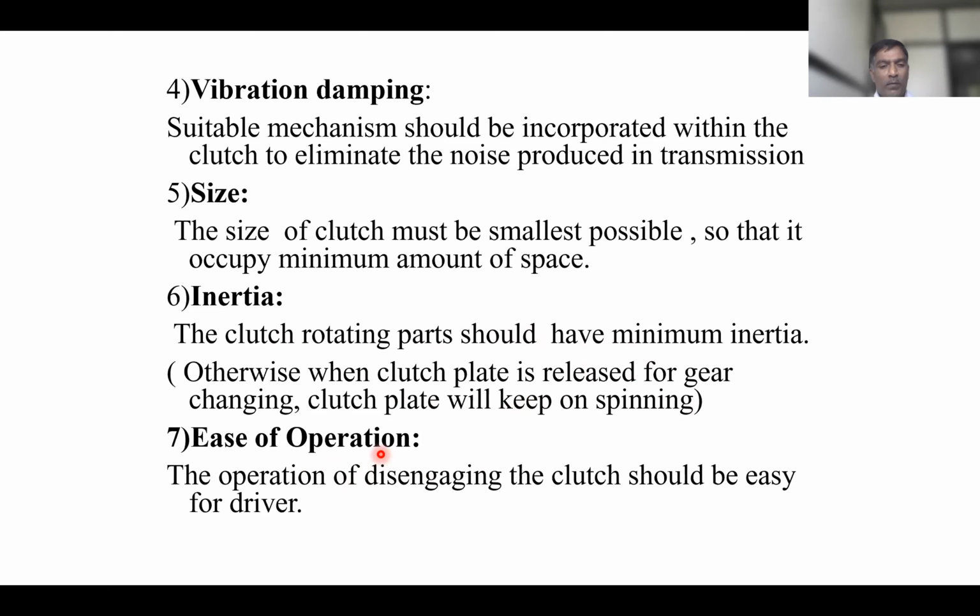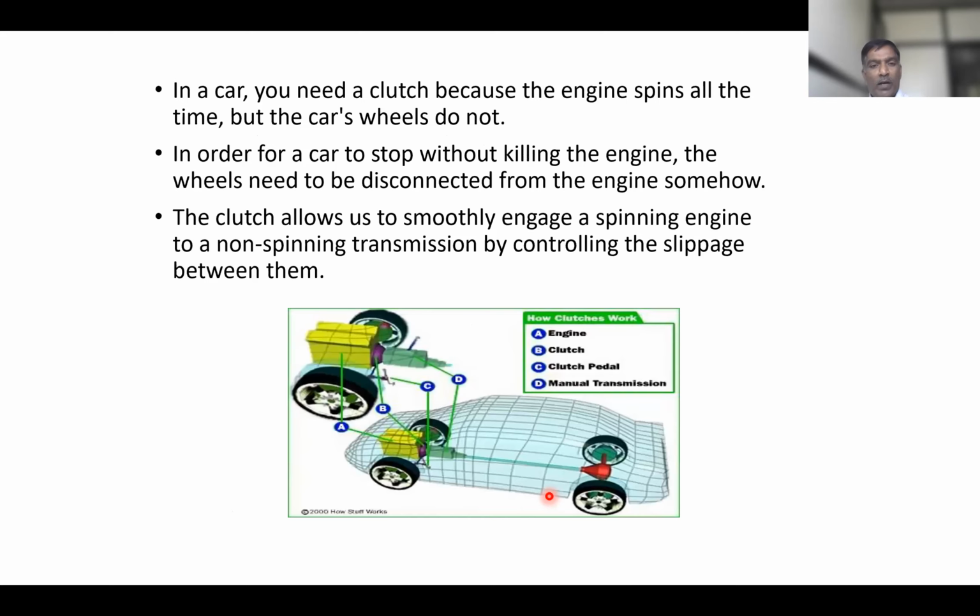And the next requirement is ease of operation. The operation of disengaging the clutch should be easy for the driver. Whatever external force is applied with the help of the spring, if it is more, then more energy is required to operate the clutch. So while designing the clutch assembly, that should be taken into consideration.